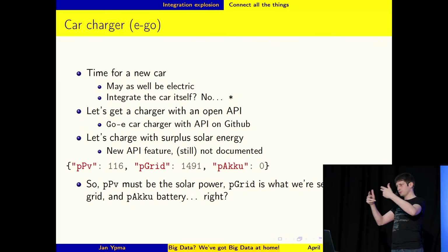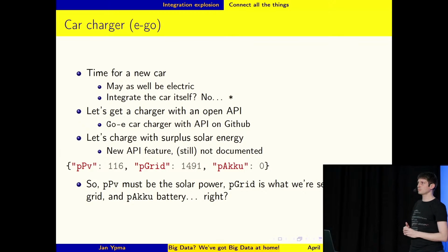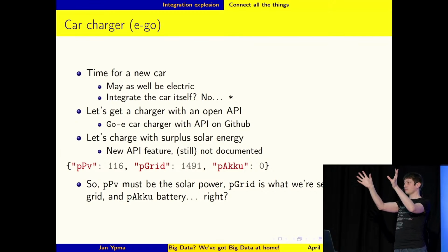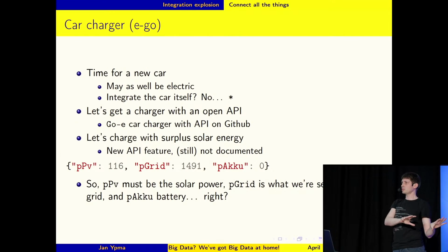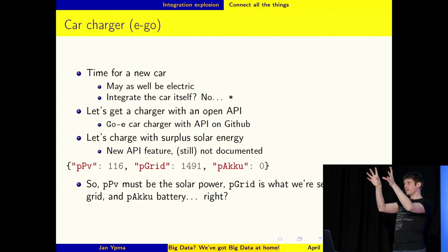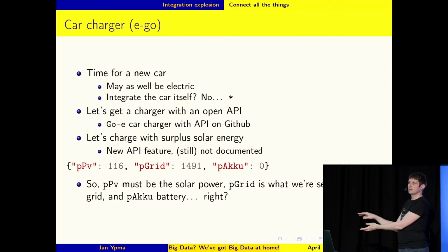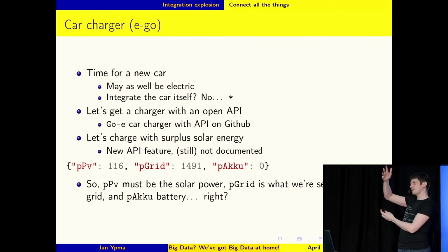Again, put these two things together, and now it's possible to look at your inverter and see, okay, we have so much sun that our battery is fully charged and our home is not using anything. Normally we would be giving the rest to the grid, but this exact rest of solar power, let's put it into the car instead. And this actually follows the sun minute to minute.